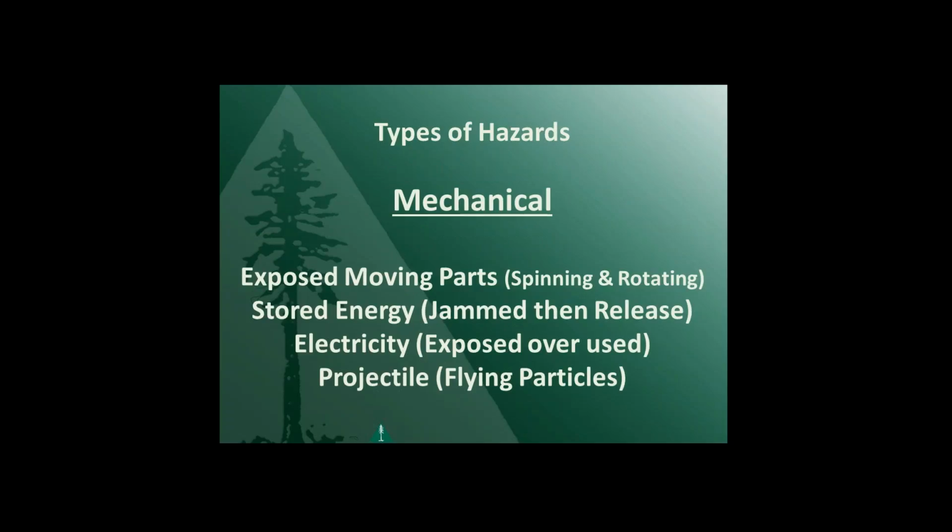If we do, how do we manage those? Well, through machine guarding. So we'll look at mechanical hazards. We have to find throughout our facility, in this hazard assessment, the moving parts. Now, is there stored energy? Like if we have a jam and then we get in to remove the jam, is something going to start back up and crush somebody? We've got to look at that kind of scenario.